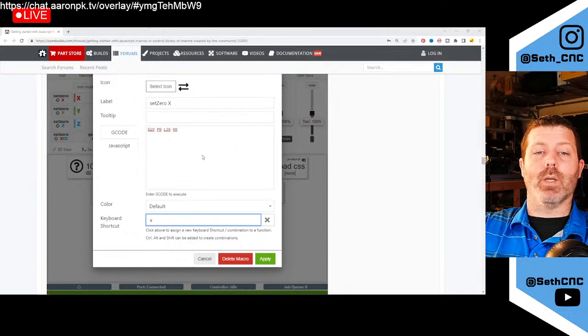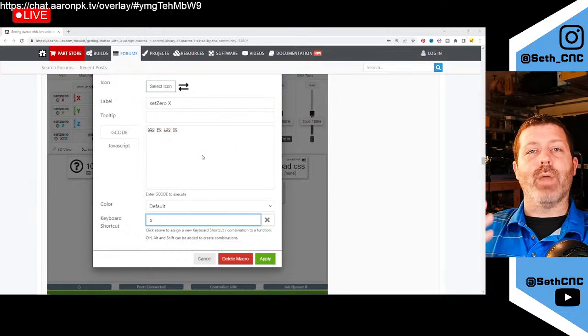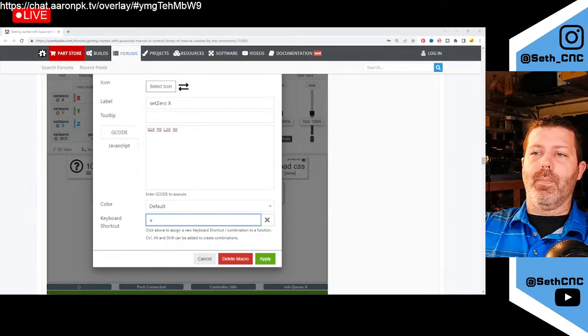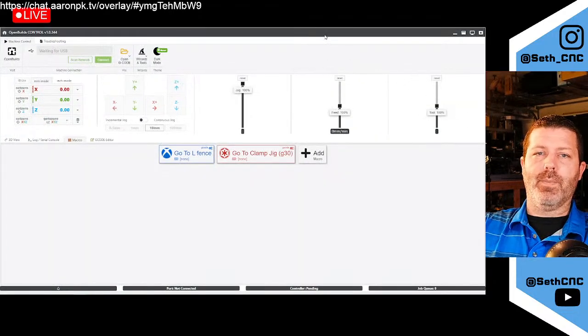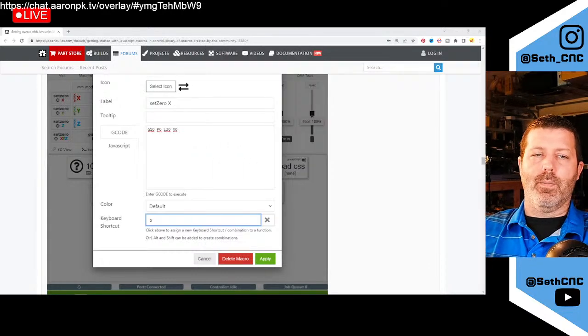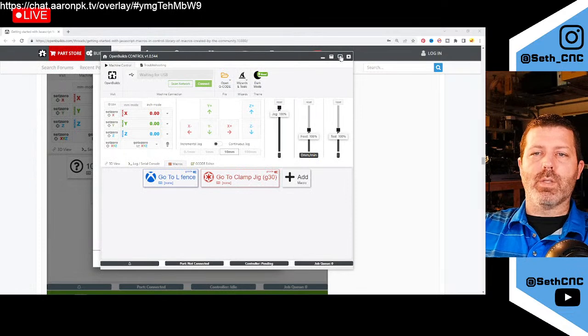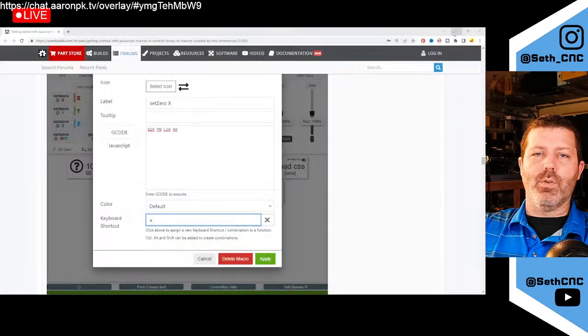I will show you guys how to set one of those up. But in order to set up a game controller in OpenBuilds, what you're really going to do is set up that game controller through Windows as a standard Xbox game controller, right? And then through that, you'll be able to map the regular keyboard shortcuts to it. Because when you set up a game controller in Windows, you basically get to map the keys how you want them to work.